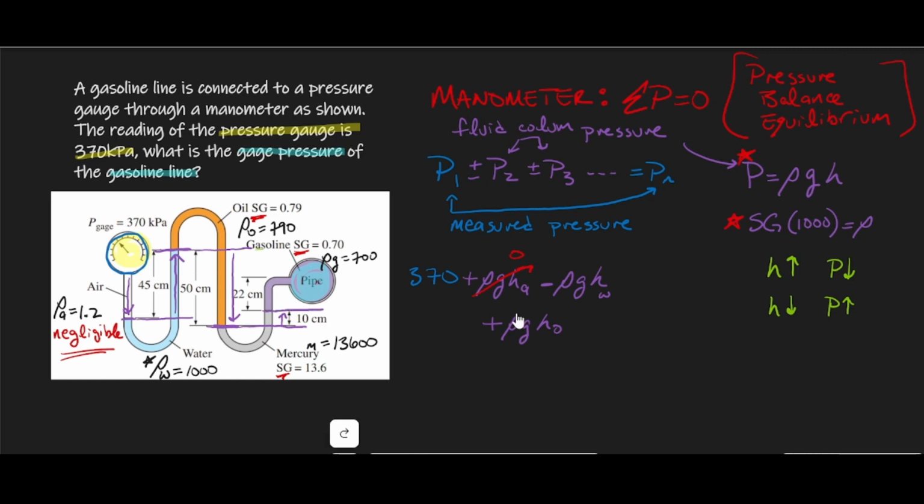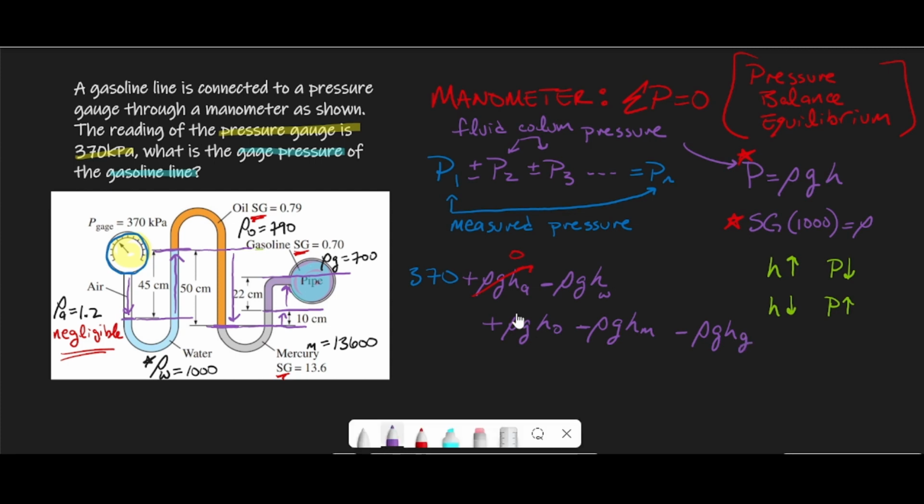Just be very careful when you're matching the height values to your materials. That's the most common mistake students make. Notice how I'm not using the curve of the tube in my height calculation. That's because in fluids the pressure is the same across horizontal cross sections. Basically the height displacement for the curved pieces is 0, so we ignore them. Use the stop point compared to the start point.